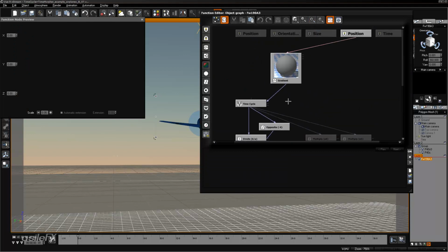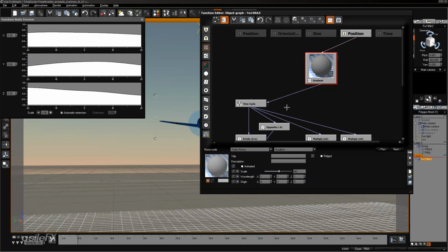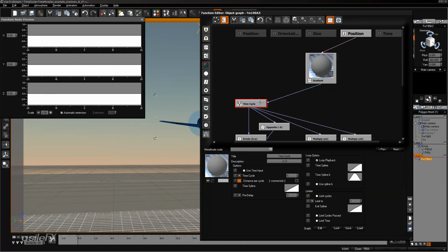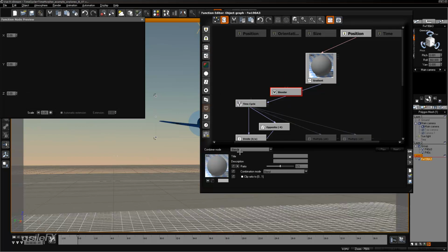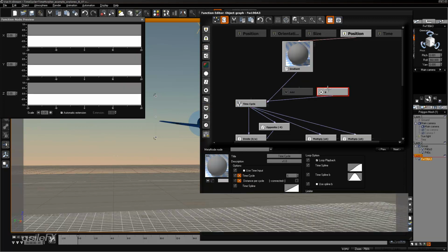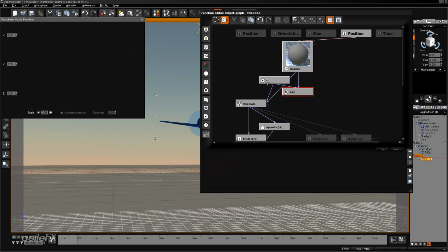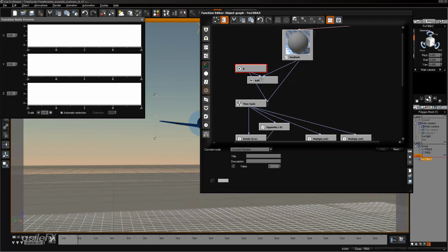We can even offset the distance per cycle or the cycle time depending on this. So if we wanted to add, we'll go ahead and add a combiner node, extract our time cycle of 6, connect that, and then connect that to our gradient, and replace that connection.